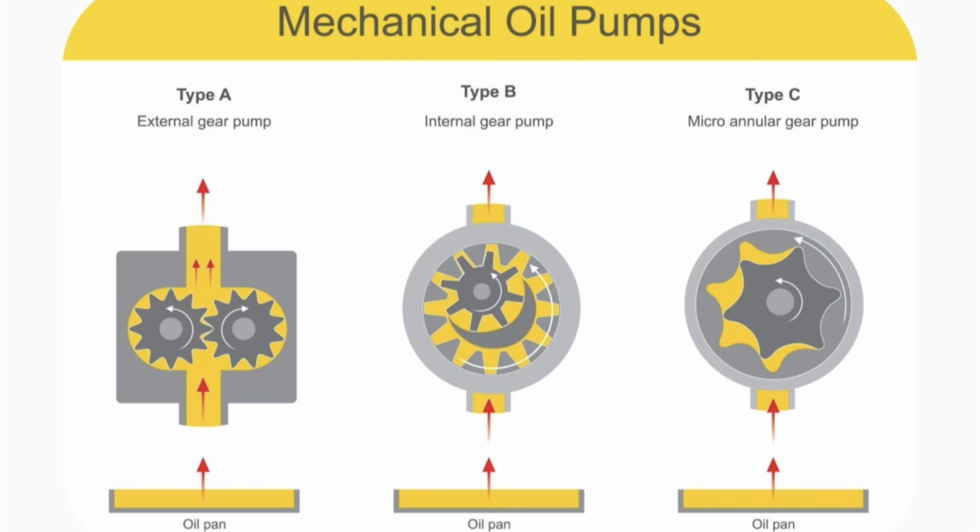Axial piston pumps: pistons sit parallel to the drive shaft and ride against an angled swash plate. Adjusting the swash plate angle alters piston stroke length, controlling fluid flow dynamically. Radial piston pumps: pistons are arranged radially, in a star-like pattern, around an eccentric drive shaft. Extremely durable under severe loads and high pressures.